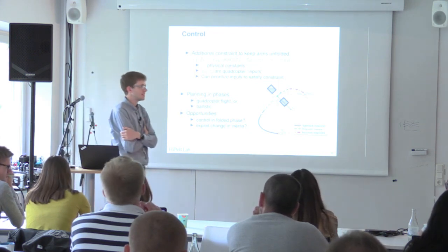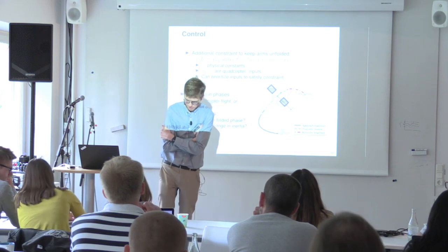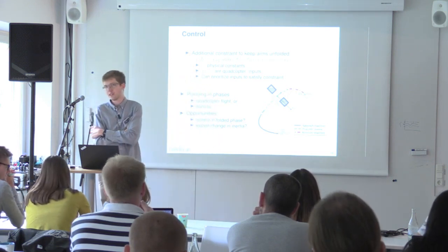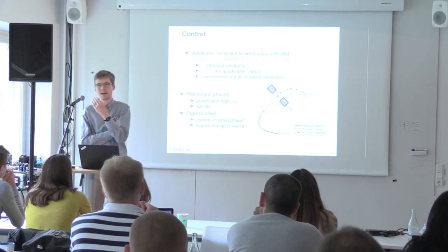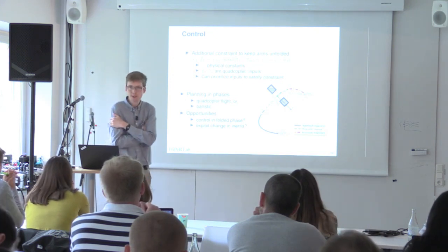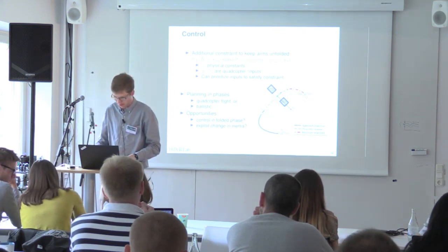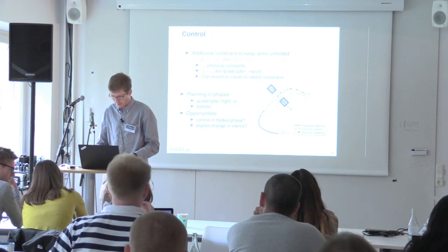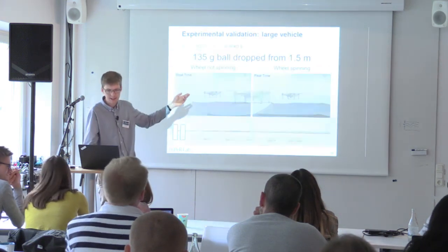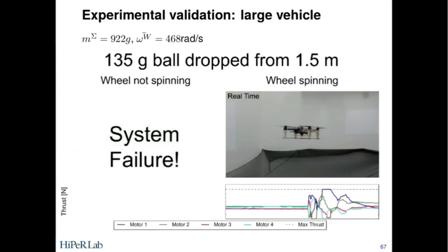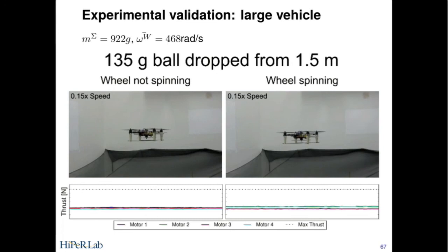So the question is, does the flywheel help you outdoors where you have rapidly changing winds and wind gusts, perhaps? Yes, that's sort of the design. That was the picture we had in mind. It should give you this additional stability. I should note, though, and I probably did not make that point loudly enough, it gives you this ability to reject disturbances better, but it does come at a cost because you have to add this additional mass, right? So every gram of weight that you put into this flywheel is a gram of payload less that you can carry, or a gram of battery less.